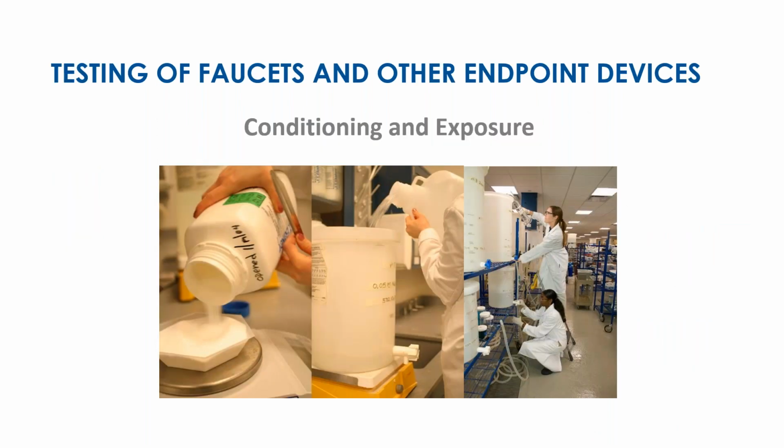So when products are tested at NSF, and specifically when they're tested for lead leaching, they are tested with a formulated test water. So this water is buffered and it is set to certain standardized water quality characteristics. In this Section 9 test in particular, the testing is performed using a pH 8 test water. It has an alkalinity of 500 milligrams per liter, DIC level of 122 milligrams per liter, and it has 2 milligrams per liter of free chlorine added as well.